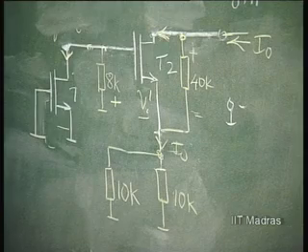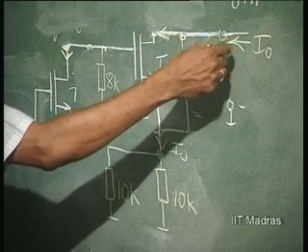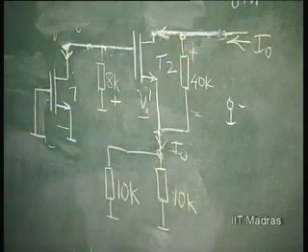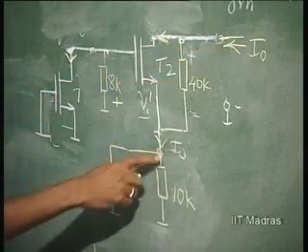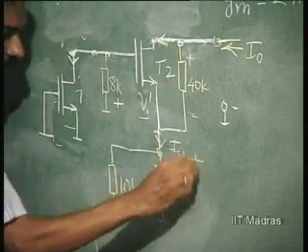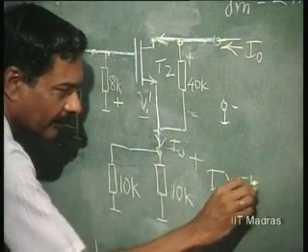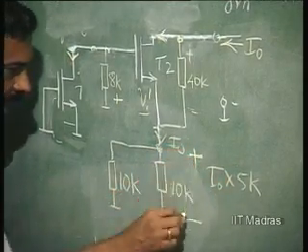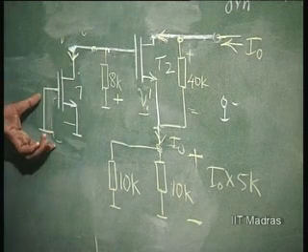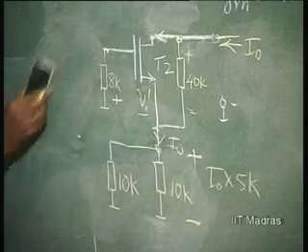G naught: obviously we have to evaluate V naught when I naught is the pumped-in current. If I naught is the pumped-in current, this is I naught, and the voltage across this is I naught into 5K. As far as this is concerned, this is useless, V I is 0. So this current source current is 0, so the circuit gets simplified very much.